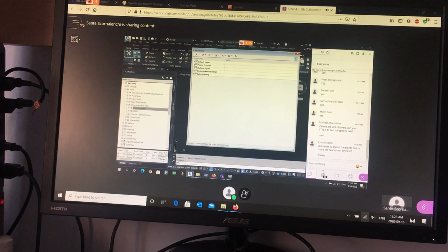When we create points, you want to make sure that the language is terrible. See, it says disable description keys, and it says true. That means if this says true, the description key is disabled. So during any function, description keys won't work, right? Because we're saying true to disable. The language is backwards. What you want to do is make sure this says false. We do not want to disable the description key.